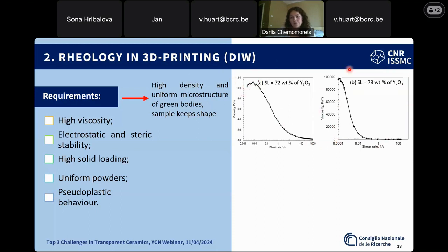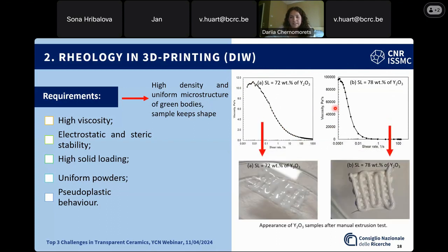What you can do, okay, I'm not an SPS expert, so if I say something that's not exactly right, I apologize. One thing is the use of sintering aids that actually help you avoid that. And the other is also possibly the use, for example, of boron nitride coating on the die, that limits the direct contact with the graphite die.